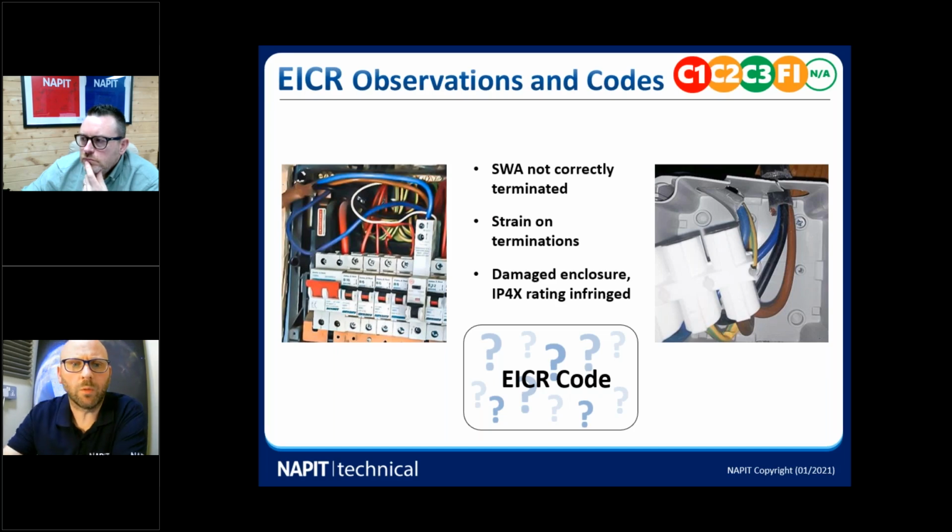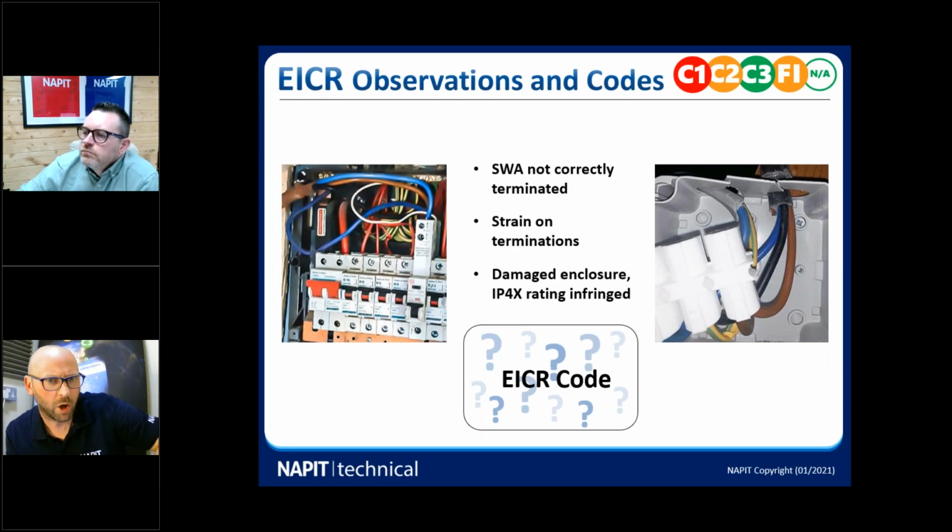Okay, so we've got a situation where somebody's made an alteration here. If you look at the left-hand picture, what they've done is they've put an RCBO in there. It's not the same brand, so we've got that issue we talked about earlier, because you don't know how good the connection is on the bottom, or whether it's venting the correct way when the device operates and lets go. So there's all sorts of issues here that only a manufacturer would be able to comment on.